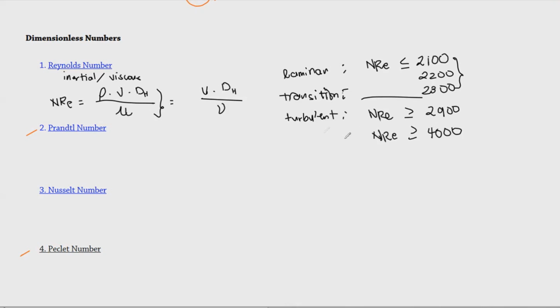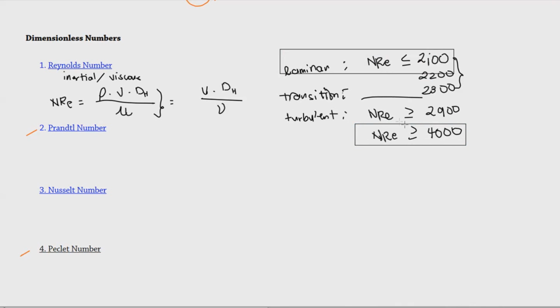There are a lot of experiments that were conducted that arrive at different values here. But since of course we have to be consistent with everyone, let's just use laminar being at the Reynolds number less than or equal to 2100, and then for the turbulent region we have this 4000, since Gene Copley's and the Perry's Handbook are using that.